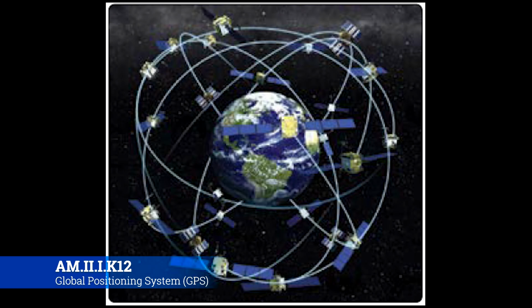Okay, so now that we know the history, let's talk about trying to understand how it works. Most radio navigation systems operate with a ground station that transmits a frequency and the airplane tunes into it or somehow interacts with it. GPS, just strict GPS, because we'll get into WAAS here in a minute, does not use a ground station, which gives it some very distinct advantages. Since you always have satellites overhead, you don't have to worry about line of sight.